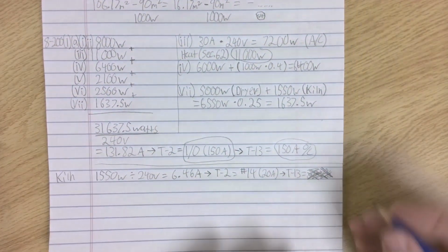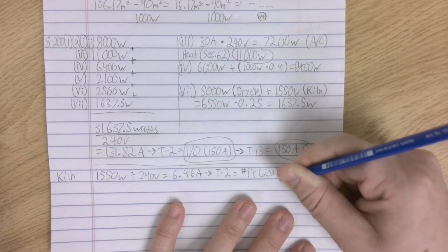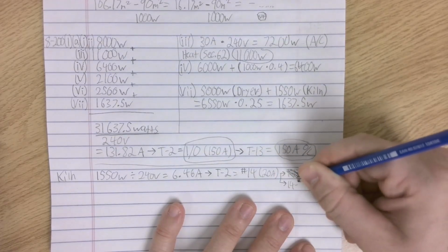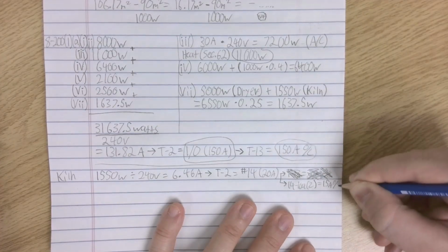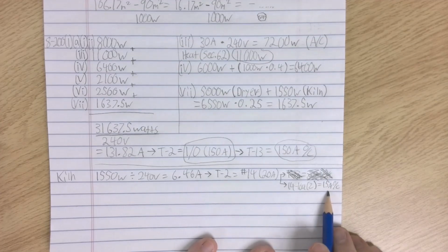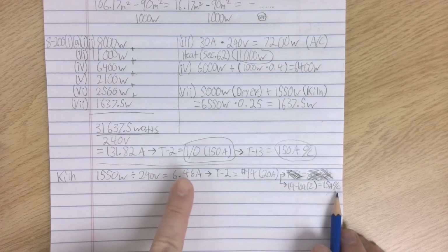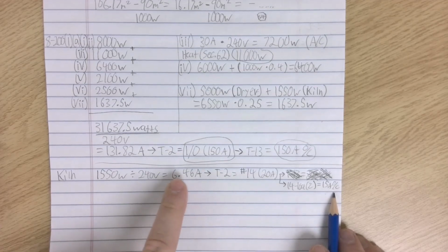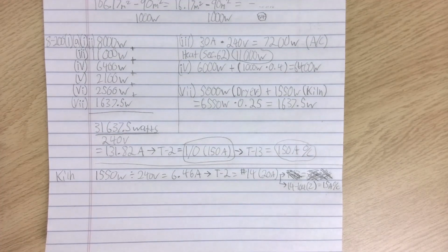So that means that it's not a 20 amp. I'm not even going to use table 13. I don't have to. I'm going to go to 14-104.2. That's a 15 amp overcurrent. But I'm still good because a 15 amp overcurrent will supply enough amperage. That 15 amp overcurrent is still going to suffice for the 6.46 amp kiln. So I'm good. I'm covered. That one's sized. And we learned about 14-104.2. So bonus.